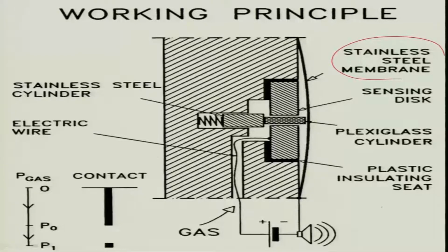Basically what will happen once you push it inside, it will not expand vertically, rather it will expand laterally. That means if I want to get the earth pressure at rest, sigma 3 by sigma 1, where sigma V is your overburden pressure, sigma 3 is your lateral pressure.